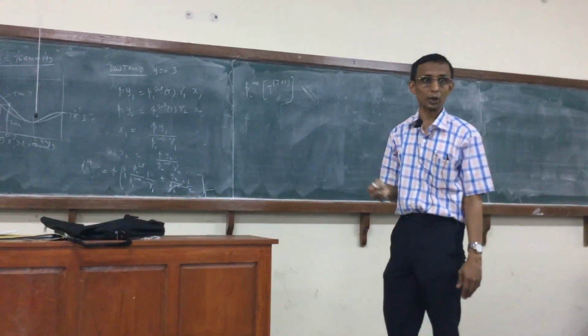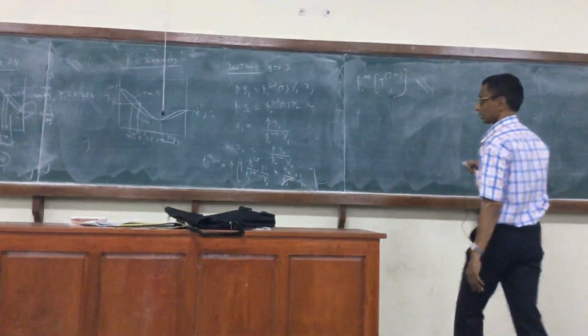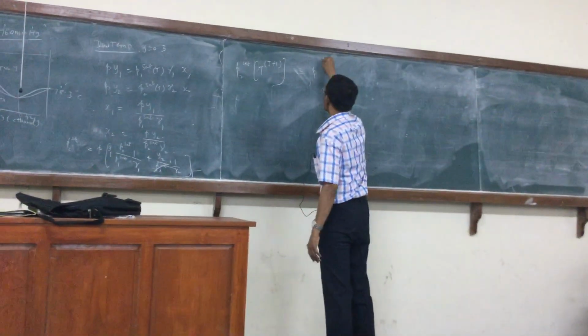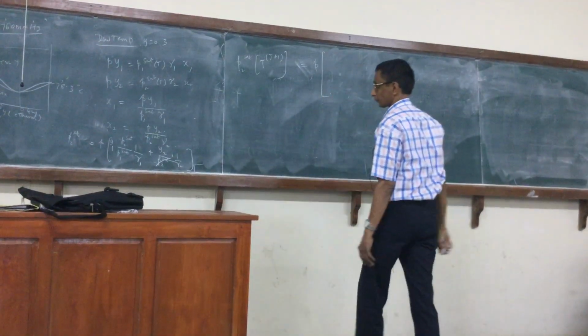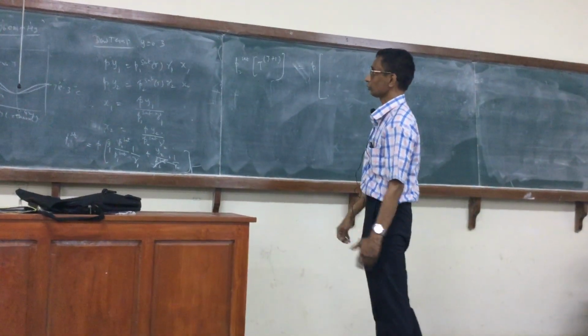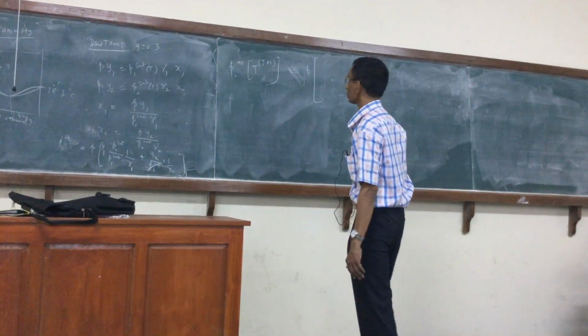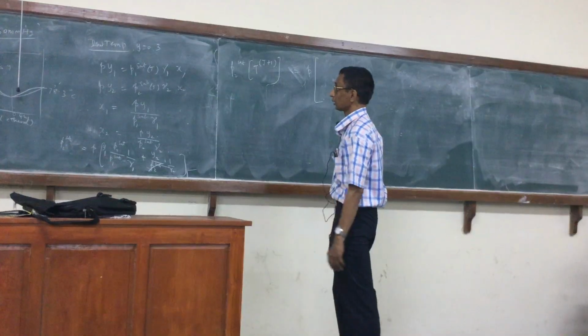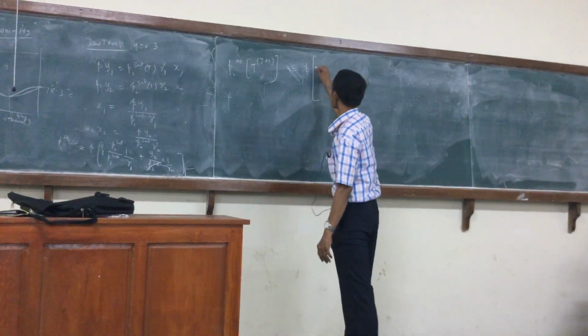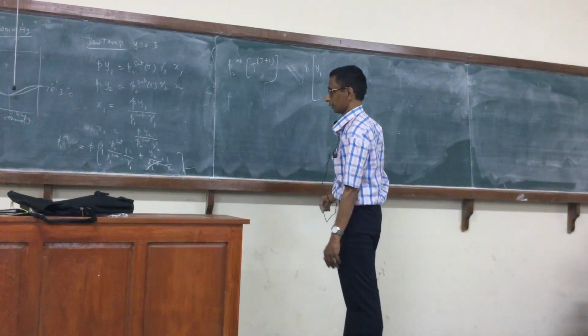The iterative formula for the temperature can be written as P times, and P is given to us, P is 760 mm here, right? So this is a dew temperature, P is given, and the y1 is also given.